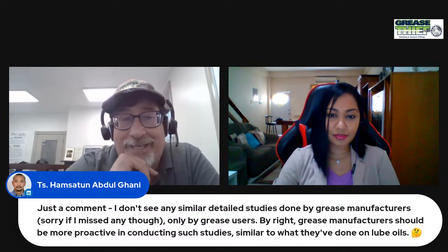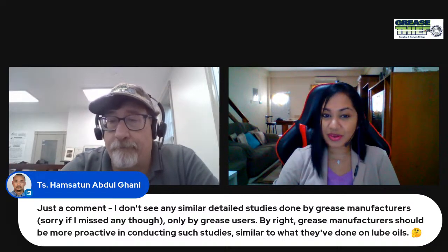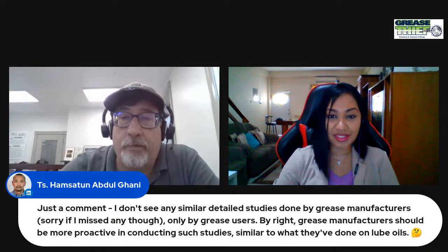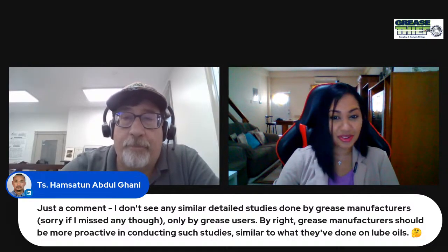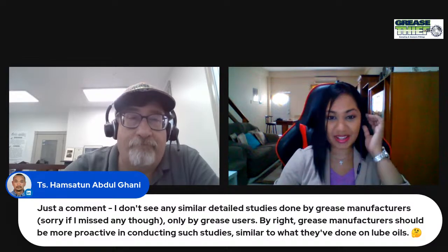And if we can't get that data, we either have to test for it or we have to take that extra effort to clean the old stuff out, because the problems that can come about through that mixture can be substantial. Whoever is telling you, yes, it should be compatible, they are not the ones handling your downtime or anything that goes wrong in your plants. So if you can do stuff in advance, get that guidance before you do all of that change out. That helps a lot. Trust me, that helps a lot.